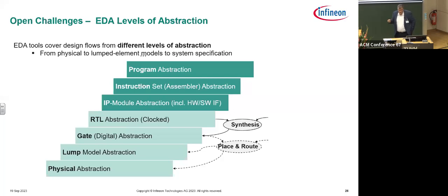We never escape layout rule checking, physical verification, classical STA, because that's our guarantee to the customer, hey, our thing works. What we want to do is to come with a quite high confidence and say, okay, in almost all cases, we will make it.